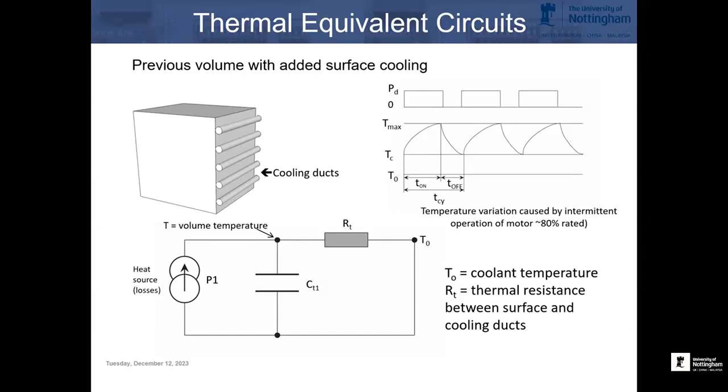And we have the thermal resistance, so where we have links between any two thermal volumes, we're going to have a thermal resistance. And we went through a couple of little examples where we showed how we can actually do simple calculations on these, and if we know the values of those, we can do calculations to work out the temperature at various points. We can work out how fast heat will dissipate and so on.